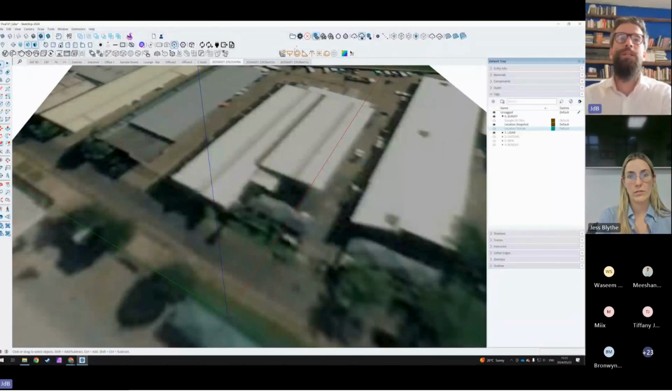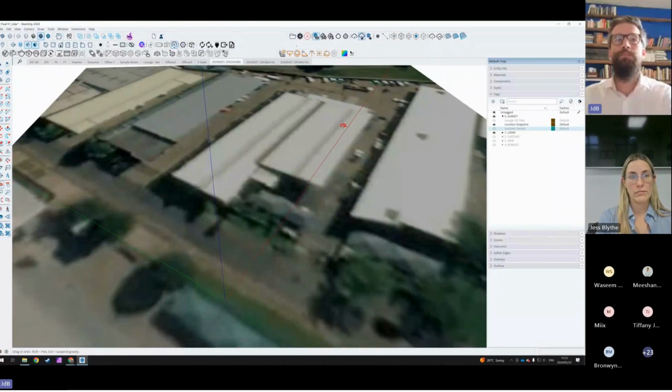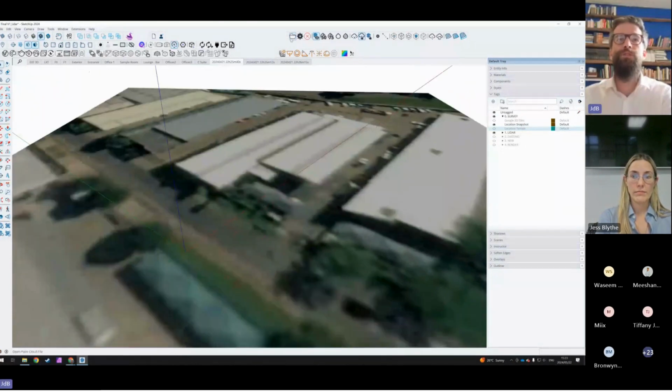The Trimble Scan Essentials toolbar allows you to load in the point cloud, and the first 3 buttons are used for loading the element in. The second part of the menu is for seeing its visibility. Then there is the way that SketchUp snaps to the point cloud, so once you start drawing 3D objects in relation to the point cloud, how do they snap to various objects? And then after that, you can clip your point cloud and even create a ground floor mesh of the total area.